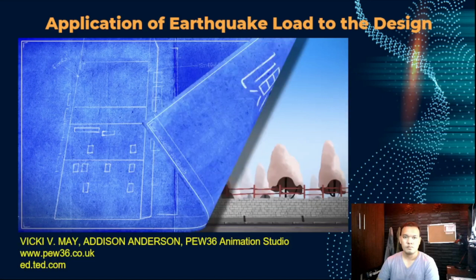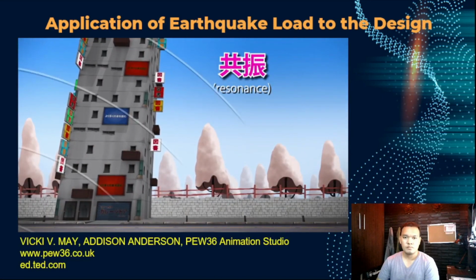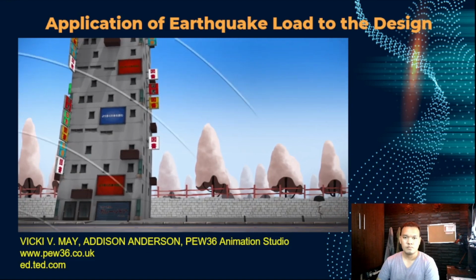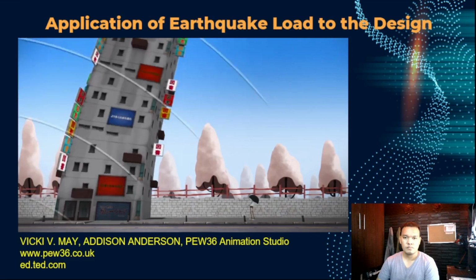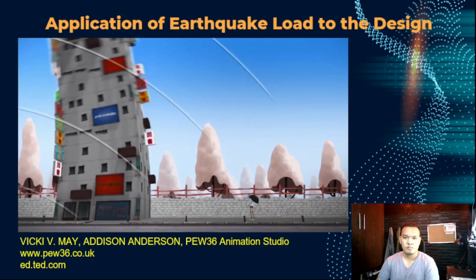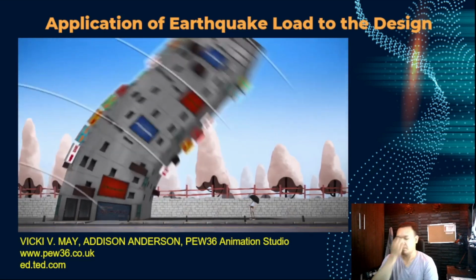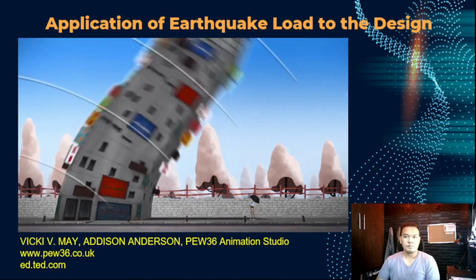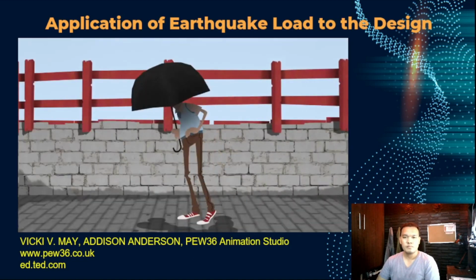What happened in Mexico City was an effect called resonance, where the frequency of the earthquake's seismic waves happened to match the natural frequency of the mid sized buildings. Like a well timed push on a swing set, each additional seismic wave amplified the building's vibration in its current direction, causing it to swing even further back, and so on, eventually reaching a far greater extent than the initial displacement.